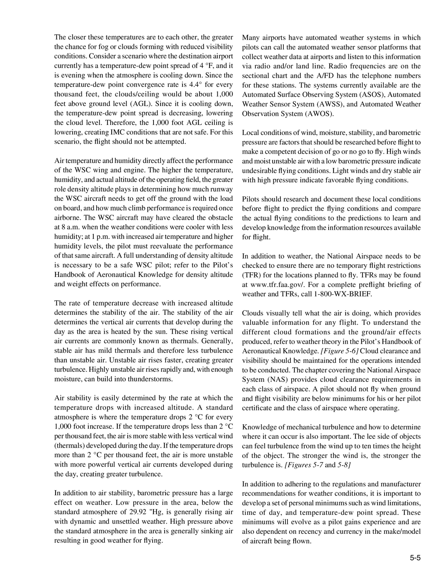In addition to weather, the national airspace needs to be checked to ensure there are no temporary flight restrictions, TFR, for the locations planned to fly. TFRs may be found at www.tfr.faa.gov. For a complete pre-flight briefing of weather and TFRs, call 1-800-WX-BRIEF.